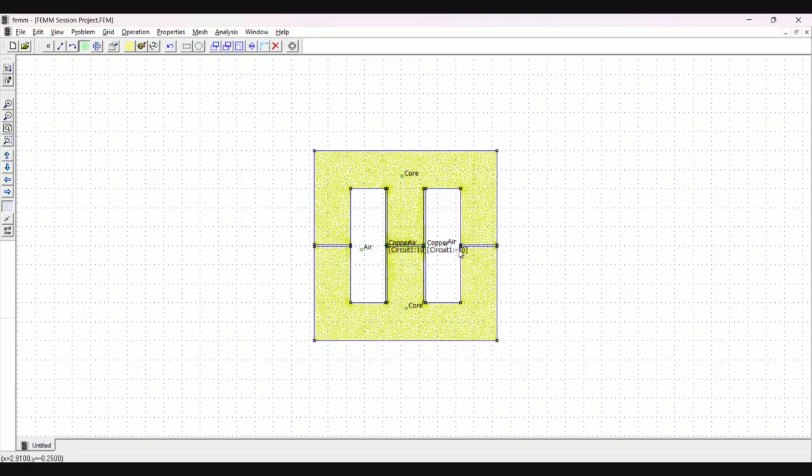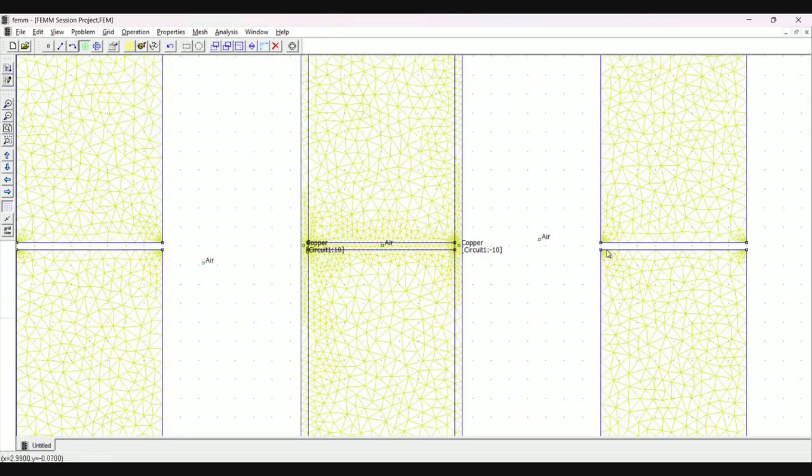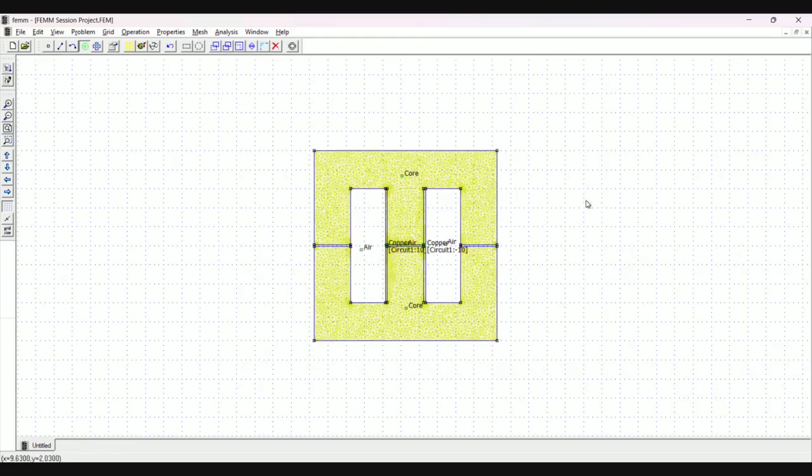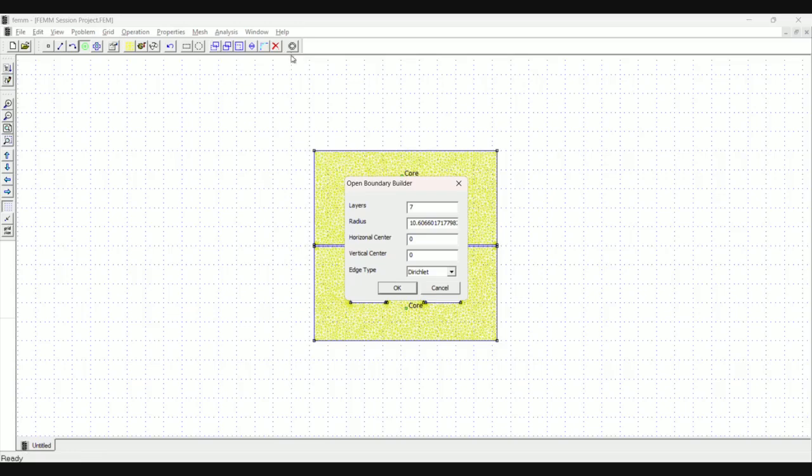Okay, so we have to break, but we have assigned air here, if you see. But if you want to break this region, if you observe, this air is flowing through this region. It's going out. Where is it ending? It's not ending. So the solver doesn't know where to solve, where to stop. So it's not understanding. So you have to have a boundary, a complete boundary. There is also one more requirement, a reason for a boundary, but for now let's understand it this way.